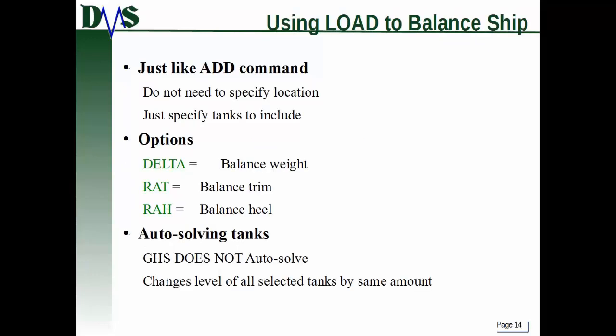Okay, so there were lots of different ways to specify loads for tanks. Guess what? There's a few extra ones. You can actually use the load command to balance the ship. And this is actually pretty common. That's what a lot of our ballast tanks are used for, is to balance out the ship. For example, balancing out the trim.